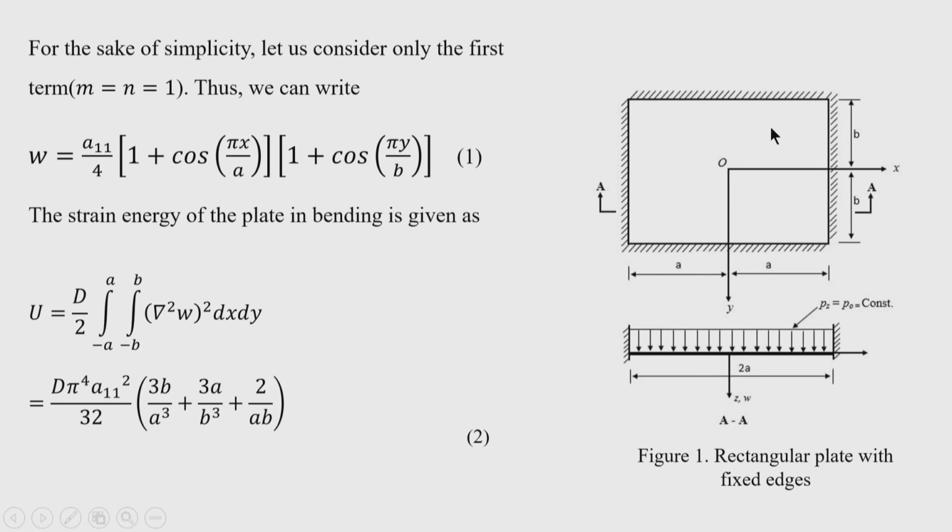the direct use of Levy's method is not possible. You can obtain it using Levy's method by several steps, superimposing the results of the deflection due to edge moment as well as the deflection of the simply supported plate with the uniformly distributed load, and then imposing the condition that the slope will be 0 for a certain value of edge moment.